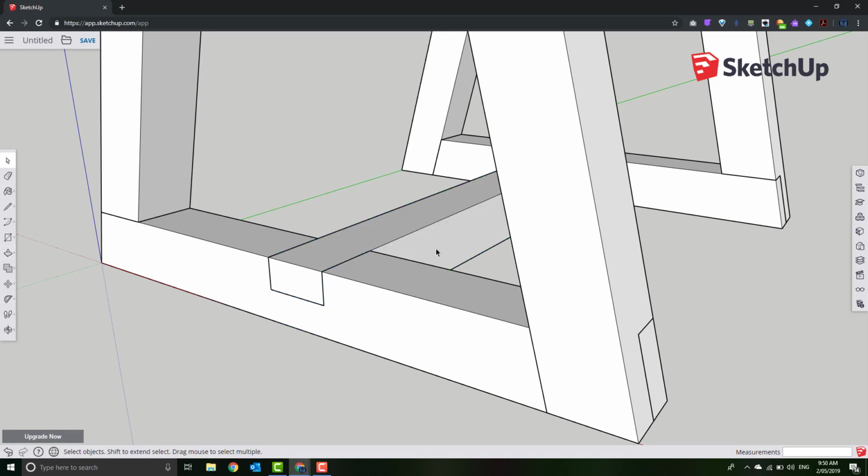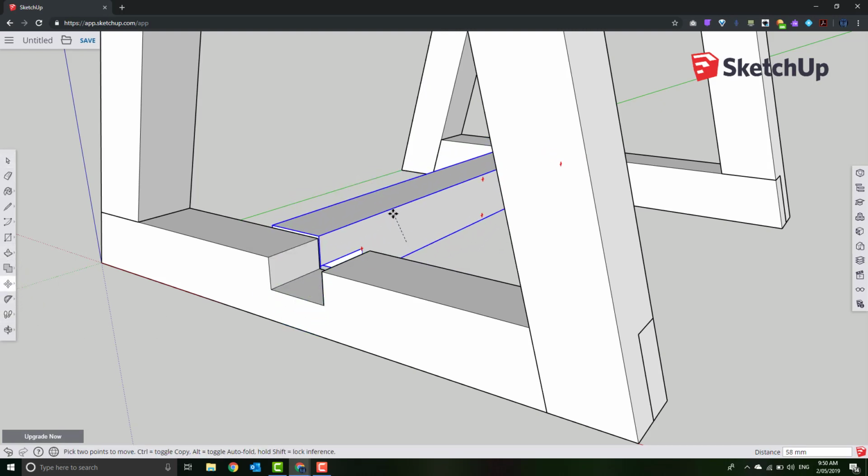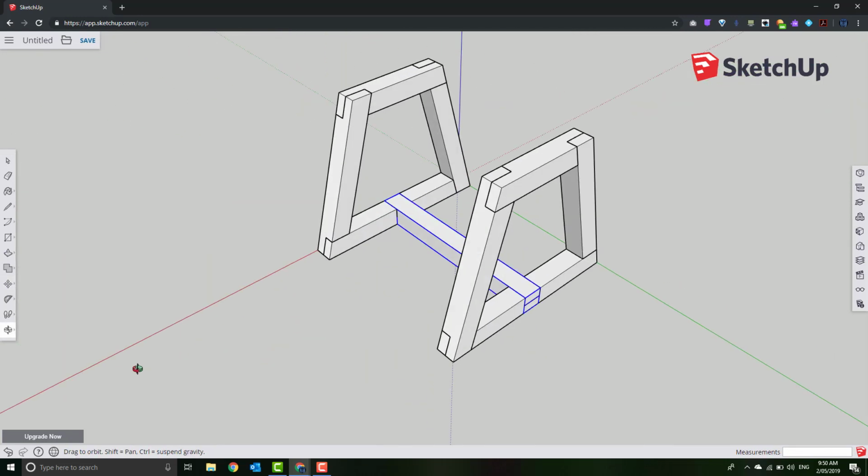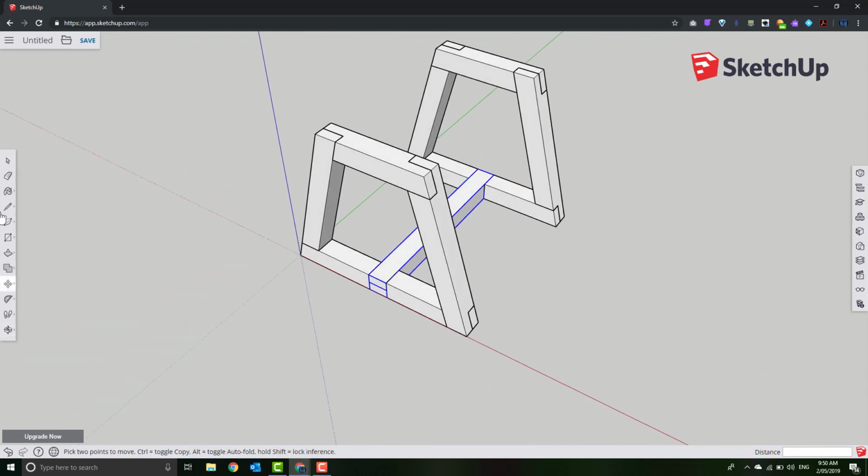And when I want, I can look at my job in an exploded view. I need to do the seat, which is roughly about 200, and we have timber at 140. Let's take 200 divided by 3. The easy way to do that is to say we know what 21 divided by 3 is: 70. We'll do 70 mil pieces, okay?